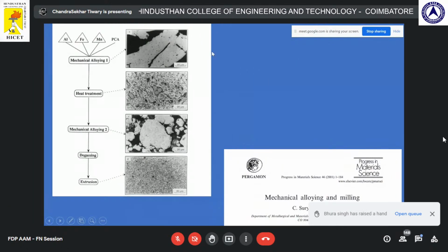In powder making, in the early days, people were doing ball milling, where they cannot really control the shape of the particle. In 3D printing, if you are using laser-based methods, the particles need to be of a certain morphology, and the size needs to be very uniform. Otherwise, it's going to choke the nozzle.